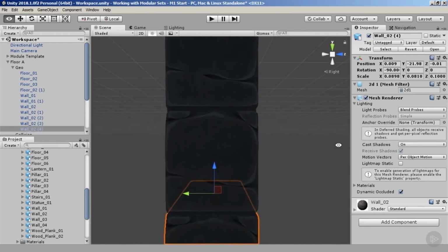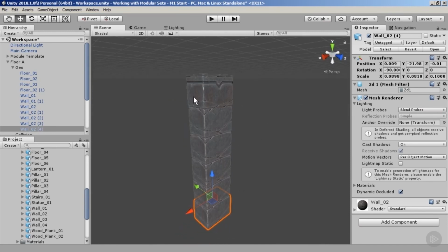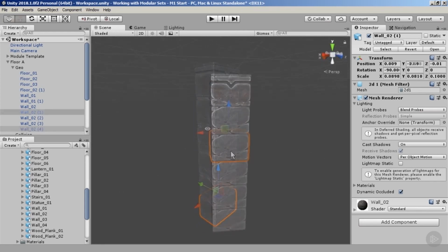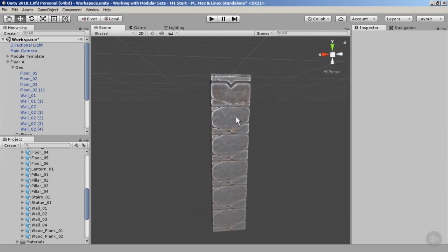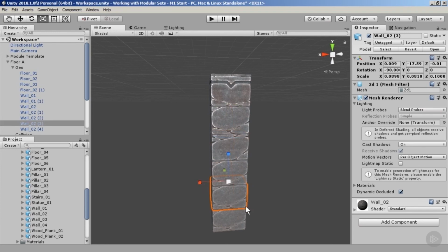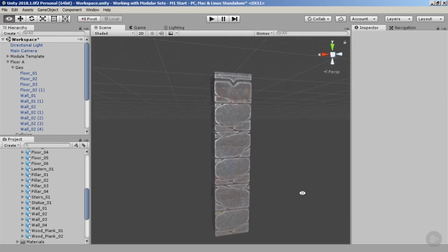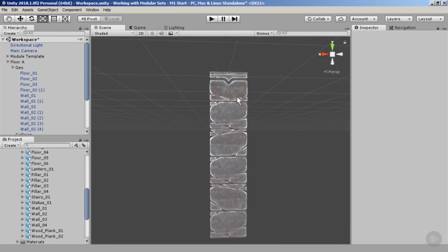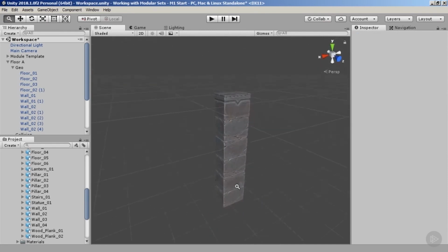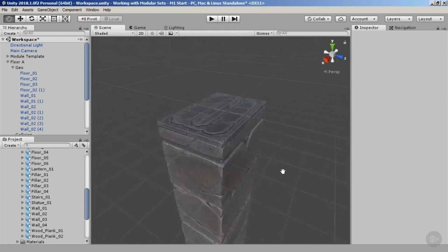Okay, and now I'm just going to pop back into perspective mode here and have a look. Let me turn off lighting. All right, that looks pretty good. If you'd like, you can spin a few of these around. There is a texture repeat, which is visible here. So optionally, you could rotate a few of these blocks. You could even scale one, again, holding Control, just to build some variation there of the texture along the side to avoid a visual repeat. So there's our first module for floor A.